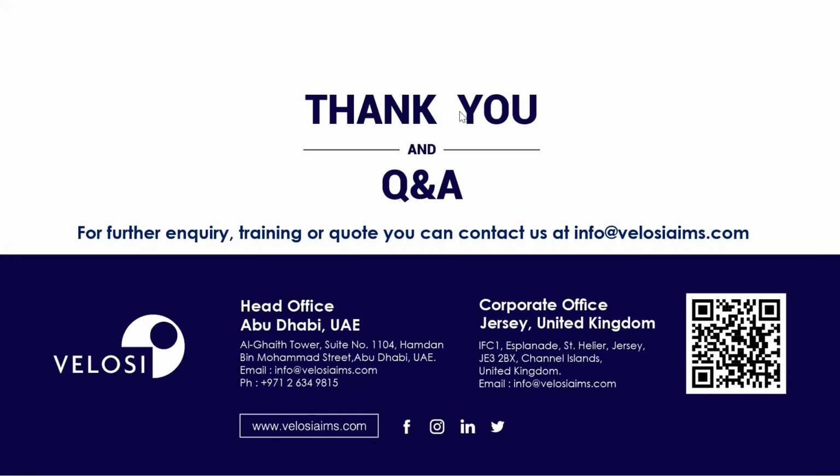Dijan, you can add to that question. Actually, for the new portions, if the column and the foundation are separate, then the new building would have the design life of a new structure, like 30+ years. We can directly assign that. But if we are modifying the older structure and adding new weights, then an initial condition assessment has to be done on that structure. If it is a single structure getting extended vertically, we need to do the condition assessment first, and then based on the factors and the NDT test results, we can analyze the same in the software also.